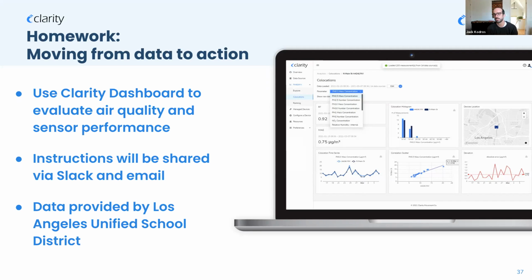On the other hand, if there's an interference with the sensor, if all sensors perform a little bit worse in certain humidity, certain temperature ranges, you may have all sensors being biased in the same direction. And in that case, you wouldn't improve your data. Well, you'd likely still improve it a little bit, but not to the point of a reference instrument. So I think it's still important to consider influences, or interferences, that may influence all of the sensors. But Matthew, you're definitely thinking along the right path there. That's a great comment.